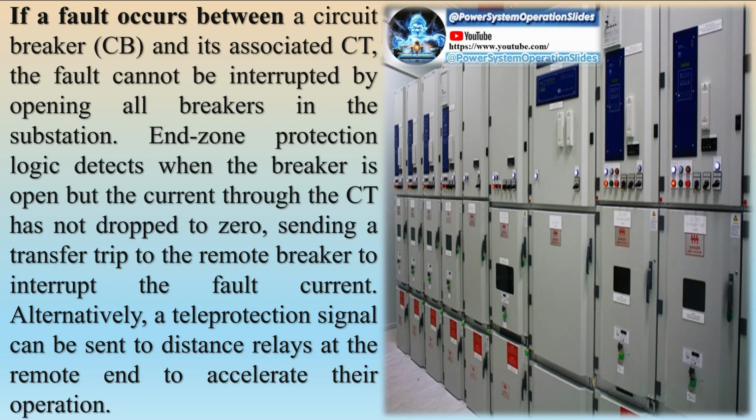In general, the main requirements for busbar protection include: security, where the probability of an unnecessary protection operation for through faults or out-of-zone faults is low; dependability, where the probability that the protection will not operate for a fault on the bus, an in-zone fault, is low; high-speed operation, required to limit equipment damage and to preserve system transient stability; sensitivity, the ability to detect and clear high-resistance faults; and selectivity, the ability to isolate only the faulty bus section.